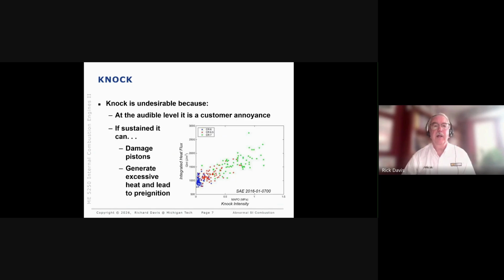So if you go to the next slide. Why do we care about knock? Basically there's two folds here. One is it's basically an audible symptom that the customer has come to associate with noises the engine shouldn't make. So it's an audible customer annoyance, and that varies by region. In the United States in particular, we've come to associate that definitely with abnormal combustion. In other parts of the world where fuel prices have been extremely high compared to the US, for example, the customer base will tolerate a little bit more knock because the engine's running a little more efficiently under those conditions.